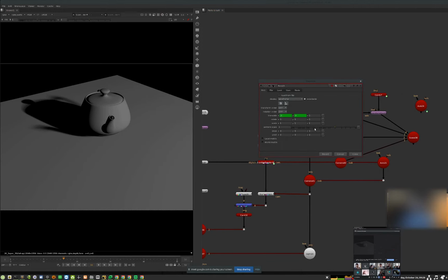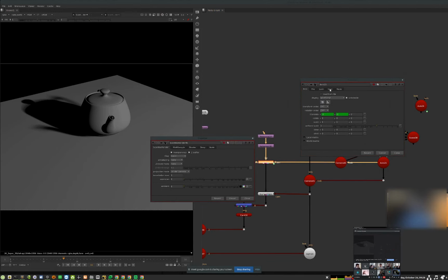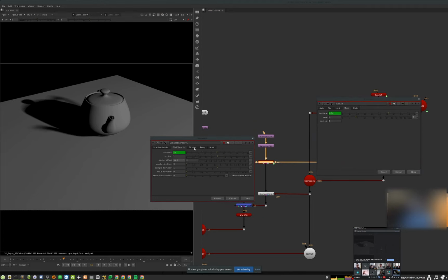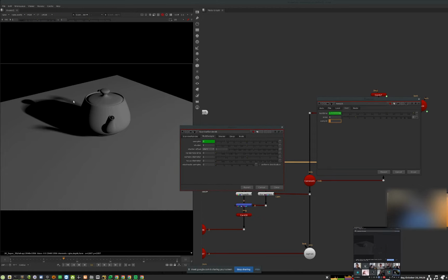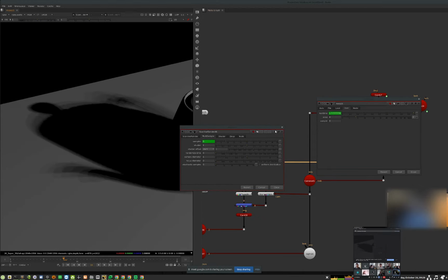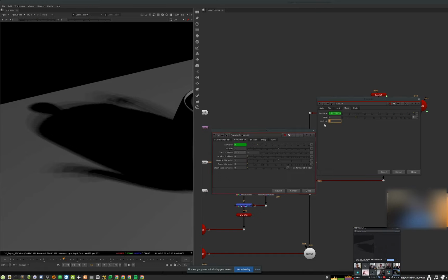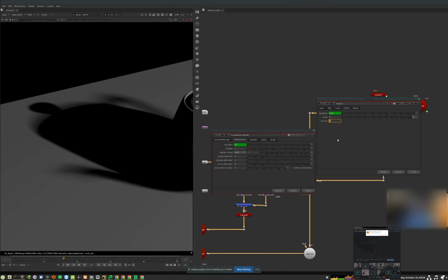And as I go to this guy, first of all, I've linked them both. Samples is 5 squared, so I have 25 samples. As I go for more samples or fewer samples, you can see over here that it will give me these kinds of things. So with fewer samples, only 3 samples. As I'm going up in samples, it will become more and more, it will converge to the right result that we want to have, which is basically how renderers nowadays work. It will just try to converge, it's when we have noise.